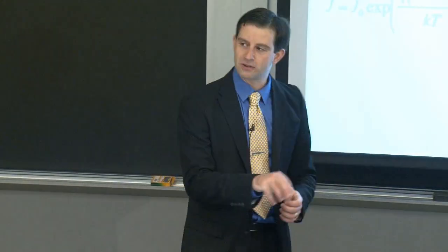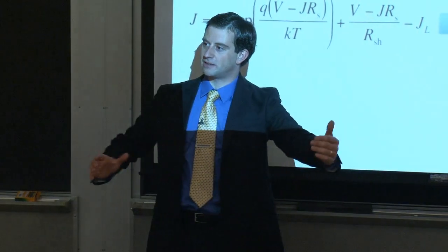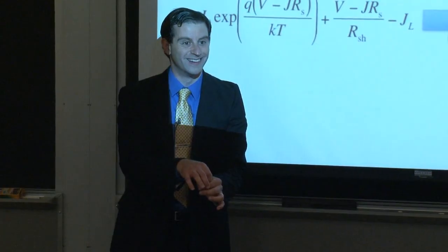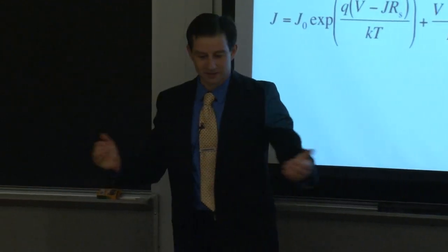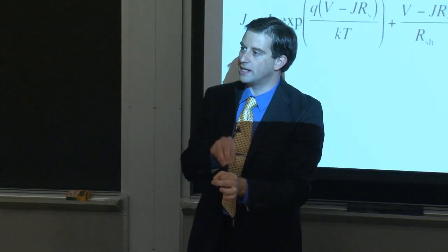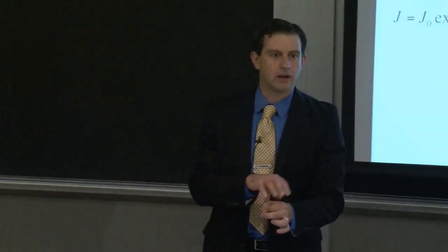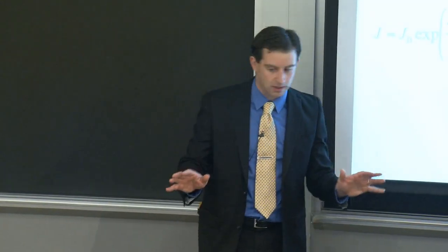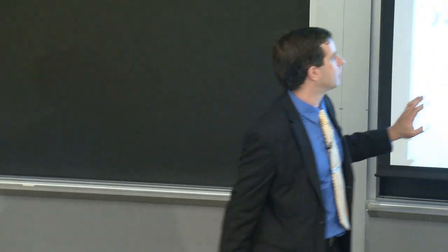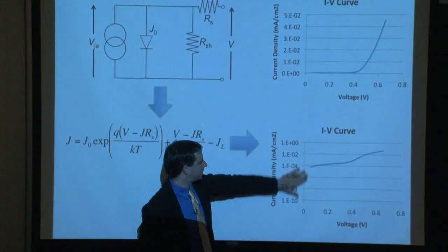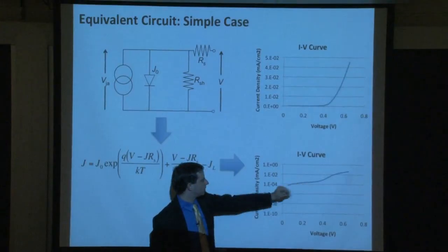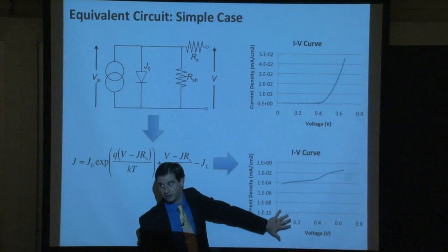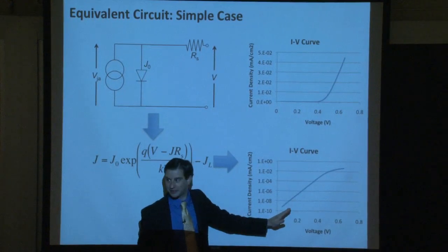And what happens at that one little spot? Well, current is flowing in from the entire emitter region into that one little shunt and locally heating up your device. And so that's why people worry about shunts in industry, because if you have current crowding into that one little spot, it's heating up, it's becoming a hot spot, and it can even melt the encapsulant materials in your module, perhaps even create a fire in extreme conditions. And so when you test the solar cell devices, typically the IV tester will measure the shunt resistance in a solar cell by looking at what's happening under very small bias conditions right here and comparing it against the healthy cell that it would expect.